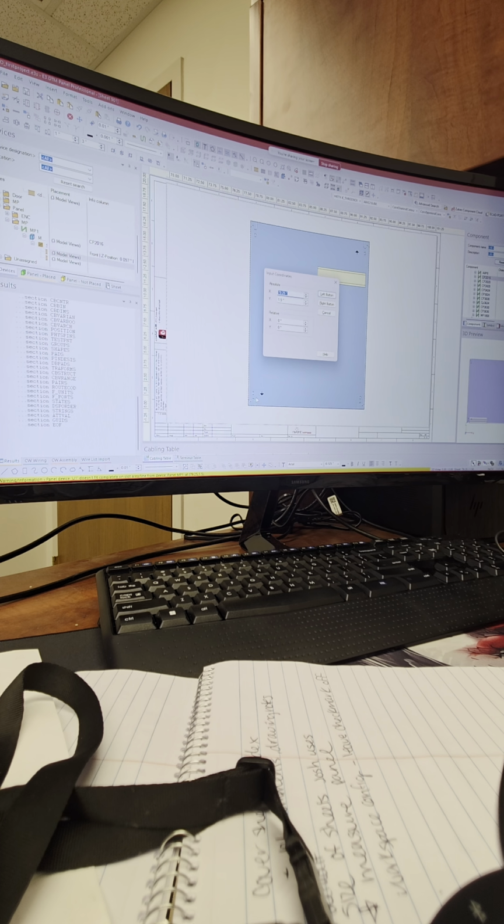Okay, now I want you to use the relative field, as in if your starting position was, quote unquote, a bottom left corner, now you can say I want my thing to move, let's say 3 inches in X and whatever, 5 inches in Y, as long as it fits on the sheet, it should be okay. And click left button to place it. So it's using your original starting point and placing it as a relative 3 to 5, as you just described. So that's 3 different ways how you can place these items in a very, very specific location.